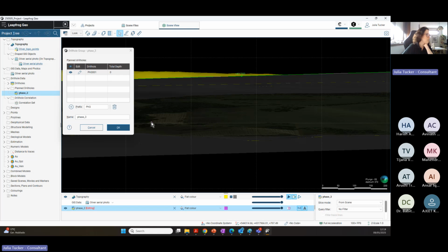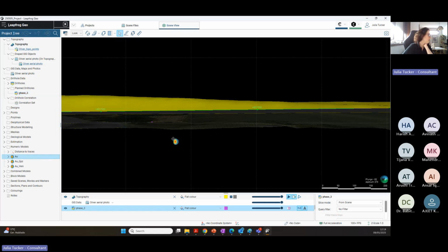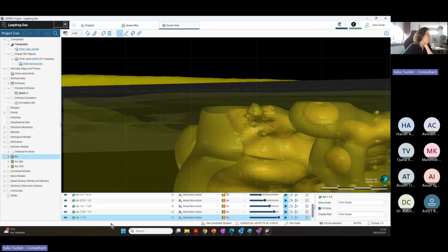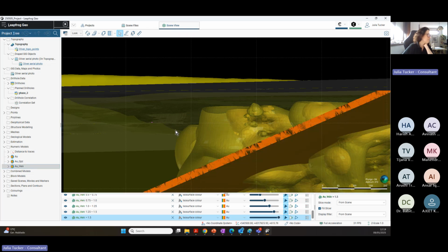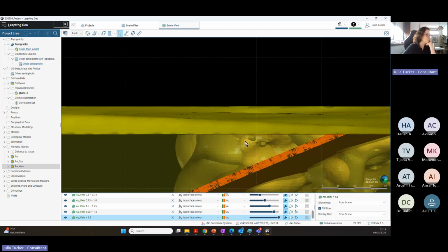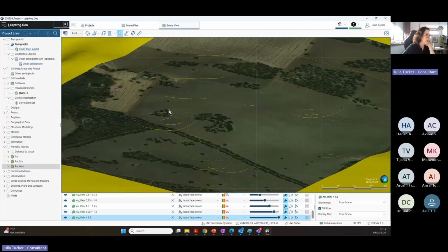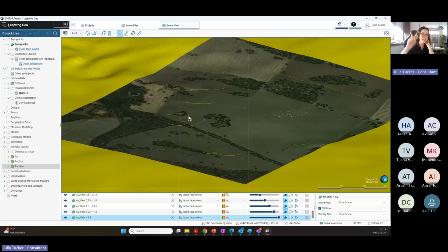So we can input right here the distance that we want this to come up, and then input our vein. And this way, we understand if our drill hole is going to intersect our already modeled vein. So this is a way that you can use to plan your drill holes and not waste energy on it, because you can already predict the place where you are going to find the lithology that is of your interest.